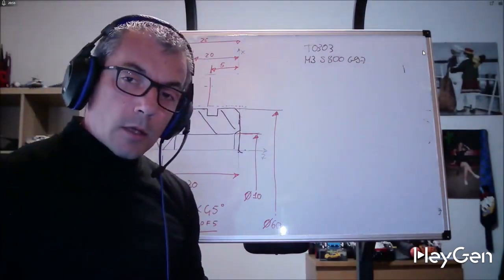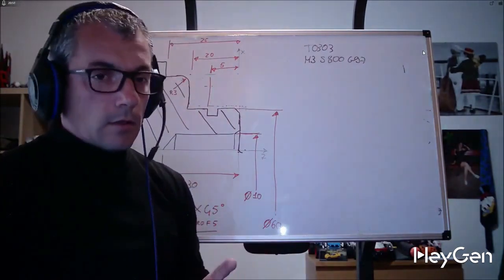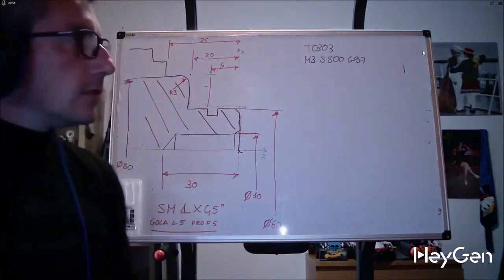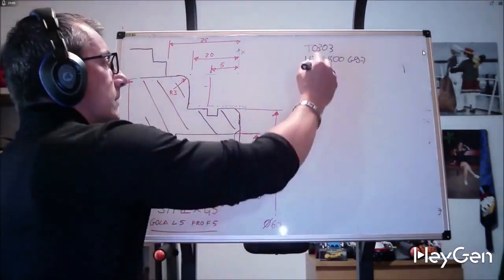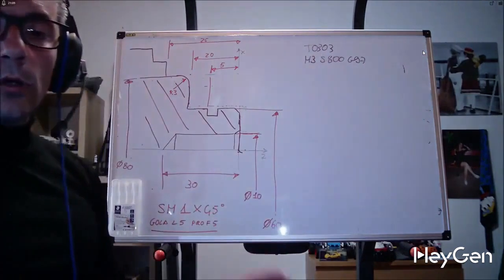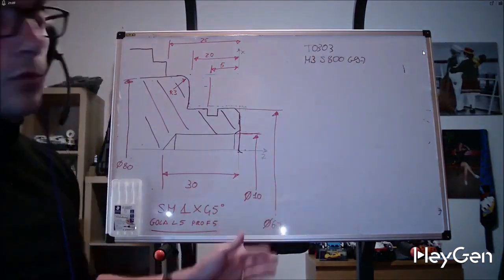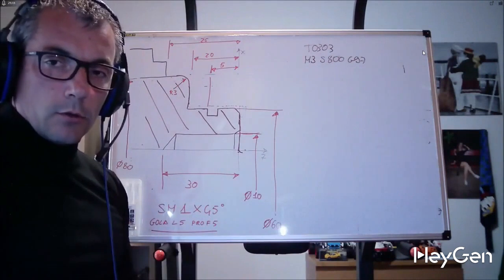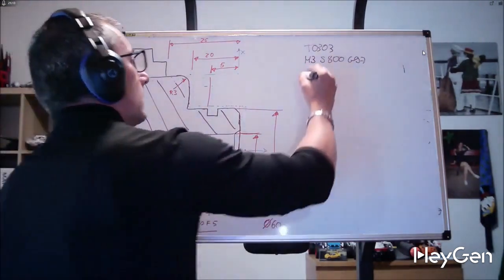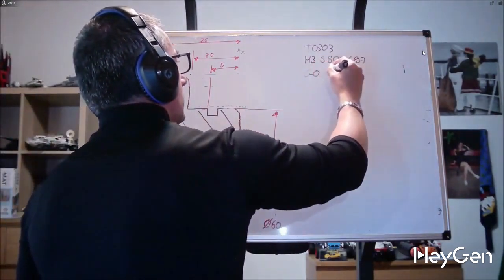The tip gets inserted carefully into position. However, since they're programmed based upon their respective diameters, one can operate them either maintaining constant RPM, or opting instead for constant cutting speed, both options providing great operational flexibility.